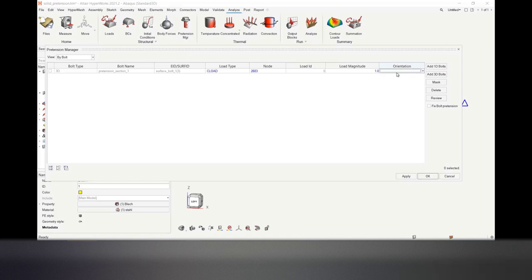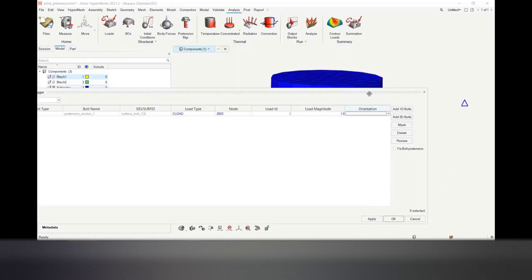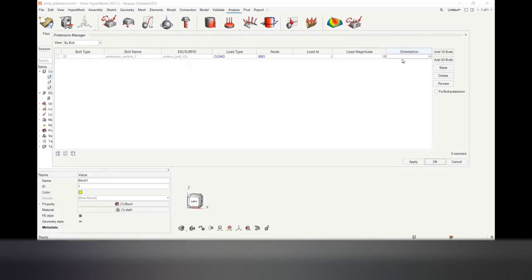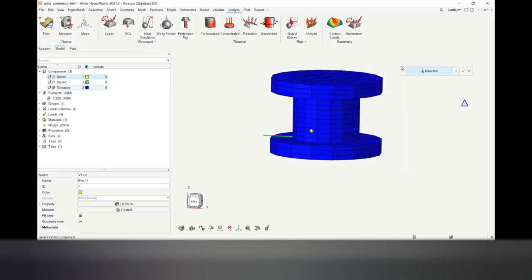And then my understanding here is that Abaqus, if you don't specify a direction, will just take it normal to the surface you've created, but I always like to just go in here and specify anyway when you move between different solvers and things. But you can just click here, it'll orient.